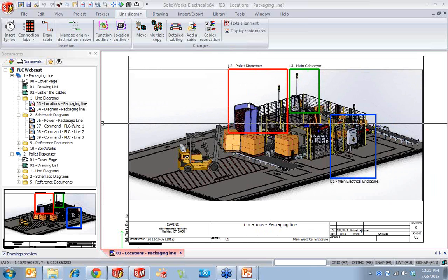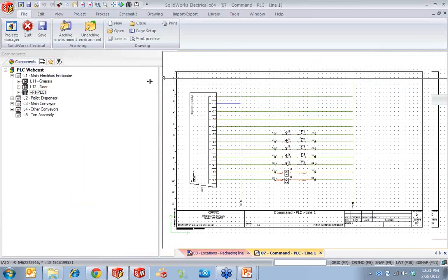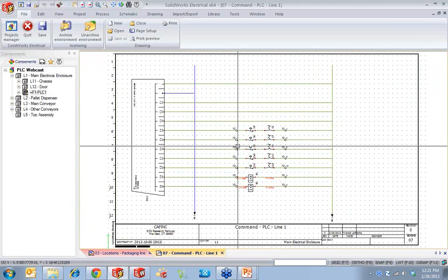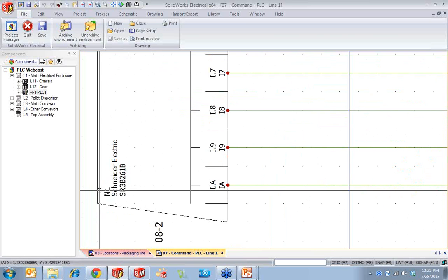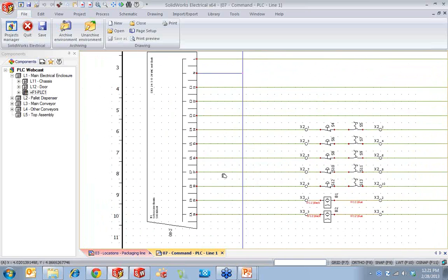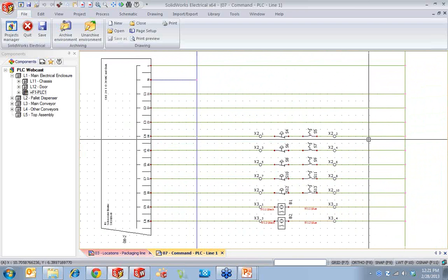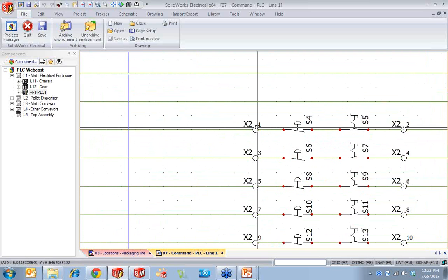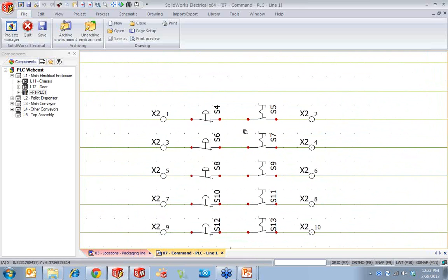And there's a PLC in each one of these things that helps control the amount of wiring and logic that's happening. So documenting this is typically done by creating a drawing showing a PLC and its I/O information. As you see right here, we have a Schneider Electric PLC with all the ports, terminals, and the wires, control and the power wire, as well as terminal strip information and the functions that that wire is connecting to.